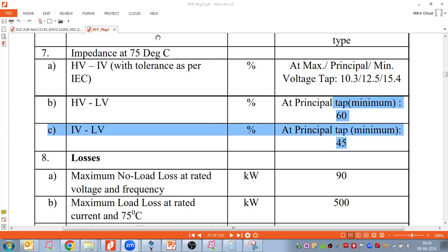Normally the Y phase current is common for the other two phases also, with a balanced load. No, sir. In the ACDB and distribution boards, we put the ammeter and CT in the Y phase only; R and B we are not providing. Which one would be suggestible, sir? This is a conventional standard practice that we follow, but I'm not sure about any standard where it is mentioned.